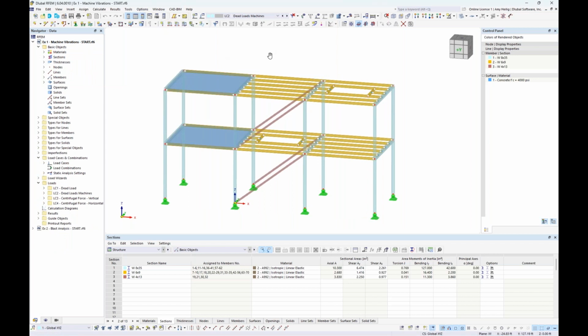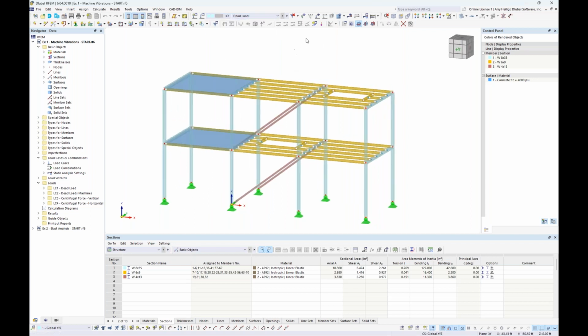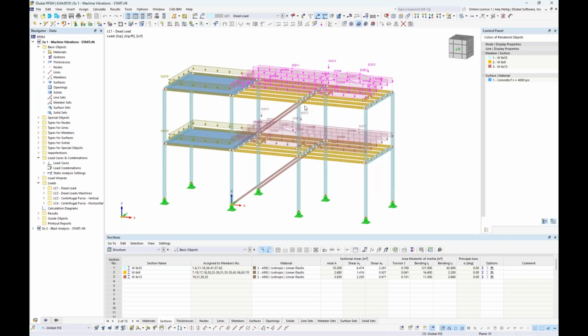So we also have the loads defined. So within the dropdown at the top, I have 4 total load cases at this point in time. We have our dead load, which is automatically going to include self-weight, but notice here that I also have applied an area load. So we have 10 pounds per square foot applied to the structure at both levels. The area load applied over on the right-hand side was used with our load wizard so that we could correctly allocate this to the members based on a one-way area load distribution. So we can right-click to display separately to see those magnitudes here.